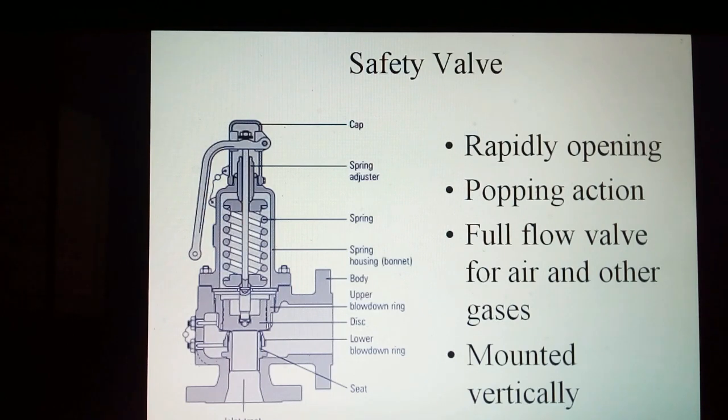The primary purpose of a pressure release valve is protection of life and property by venting fluid from an overpressurized vessel. Many electronic, pneumatic and hydraulic systems exist today to control fluid system variables, such as pressure, temperature and flow. Each of these systems requires a power source of some type, such as electricity or compressed air, in order to operate. A pressure release valve must be capable of operating at all times, especially during a period of power failure when system controls are non-functional. The sole source of power for the pressure release valve, therefore, is the process fluid.